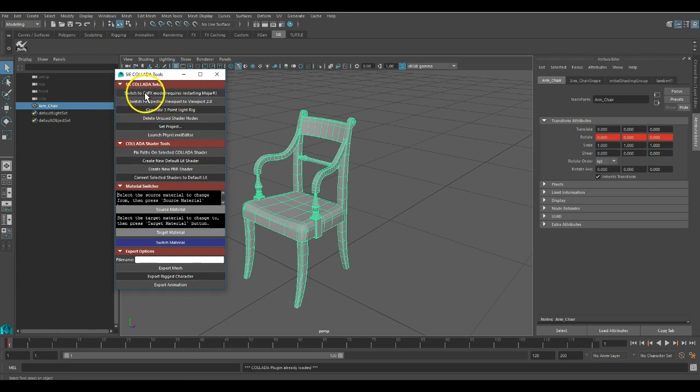Okay, so the top part is switch to CGFX mode. The first time you run this, or if you want to run it in a mode that allows you to preview this stuff, it will have to be running in CGFX mode. By clicking this button, it will set up the environment to allow that to happen. Mine's already set up, so I'm not going to do that. But if you click it, you'll have to restart Maya for the changes to take place.